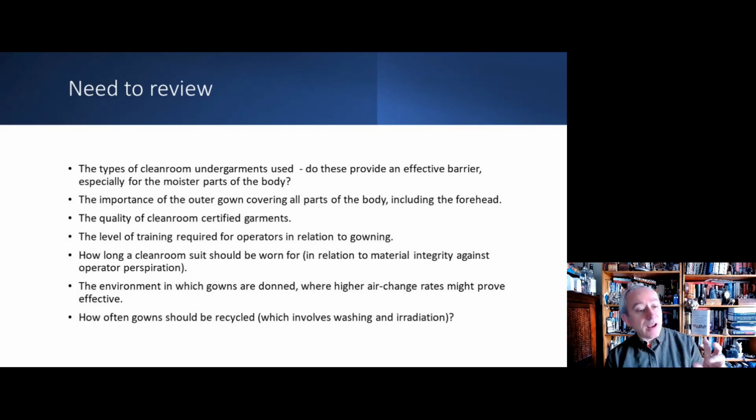We have policies on how many times a suit can be relaundered, which is set at about 50 times. But if there's any damage noticed on that suit, then that suit needs to be thrown away, because anything that could risk the integrity of that gown means that you've got a structural weakness. You know, with the shirt that I'm wearing, if I get a slight thread here, eventually that's going to unthread and break. I can wear that for quite a few washes. It doesn't really matter, but it does matter in the clean room, because that is a point of weakness, and that could lead to a contamination event that we don't want to be faced with.